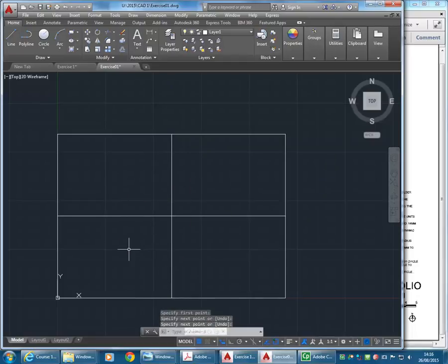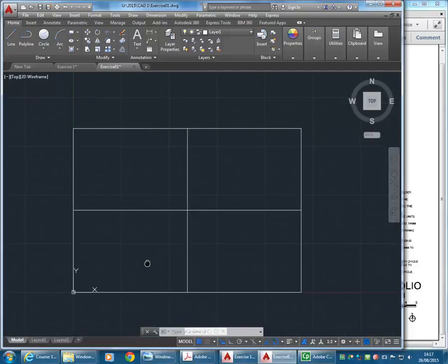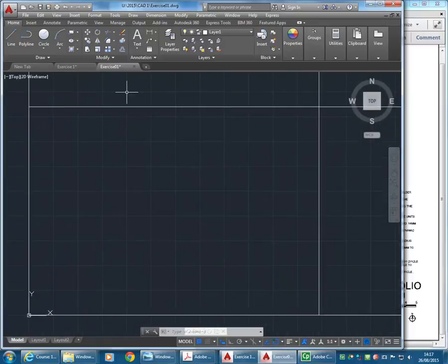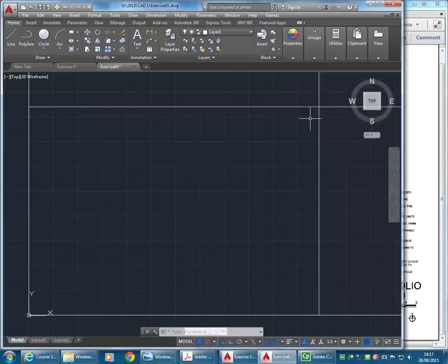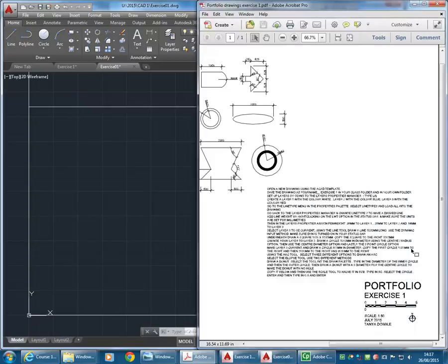Okay, so when people say half the size, they usually mean a quarter the area. So 50% of the size of an A4 is actually a quarter of the area, because it's half in each direction. So 1 to 50 would be a quarter of the area of a 1 to 100. And it's important to start thinking about these things. You'll get more used to it as you do more drawing as well, more hand drawing as well. So now I can zoom into that area, and that's where everything should fit. Don't worry, if you haven't drawn that dividing cross, you can still draw your shapes.